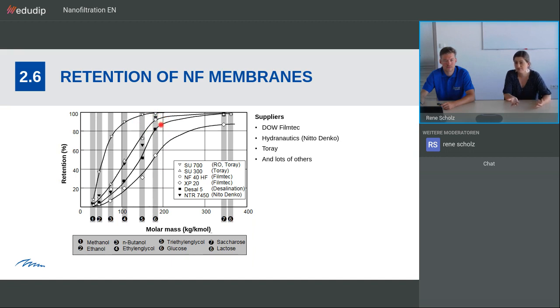And you can see that these 3 membranes from different suppliers have quite different retention efficiencies, really. So there's one membrane that is at more or less 50%, while the best one is at more or less 90%, so pretty near to reverse osmosis. It's a general effect that the types of membrane will differ quite a bit. This does not mean generally that, let's say, the membrane here that is lowest in retention is a bad membrane. That can mean that simply this is a membrane maybe that has ultra low pressure requirements. And if we have the right application where we want just a partial retention and very low pressure, this can be the membrane for us. If we want a higher retention and maybe a bit higher pressure, maybe the 3rd nanofiltration membrane, which has already higher retention, would be the better one.